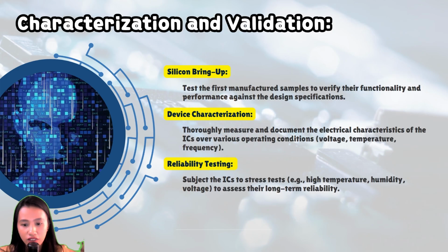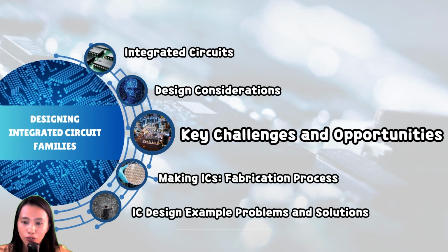Silicon bring up, device characterization, and reliability testing will be under validation. You test your ICs to see if they can withstand stress, meaning weight, high temperature, humidity, whatever kind of stress the environment can impose during packaging, transport, and then placement in stores, in devices, or factories where our IC is used, like mobile phones, etc. You need to test how reliable it is and how long it will last. So, those are the different things you have to do in designing and fabricating your circuits.